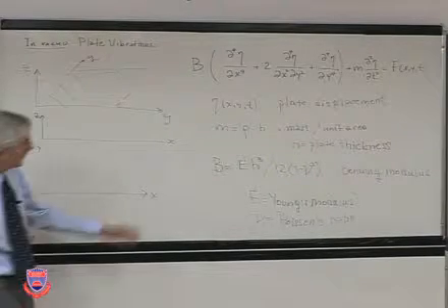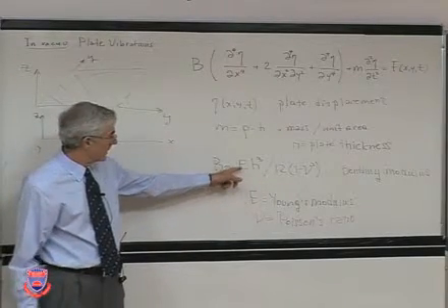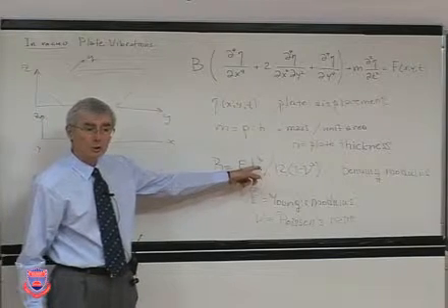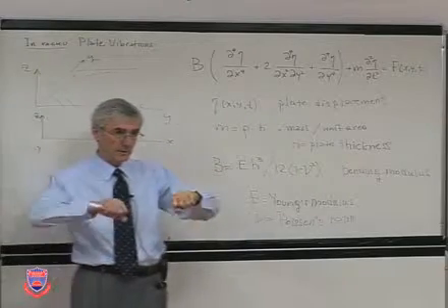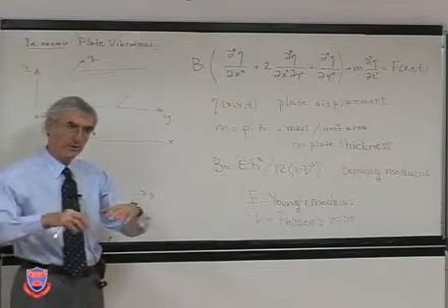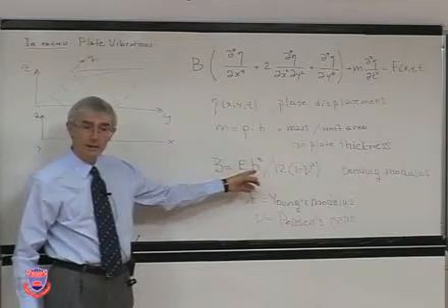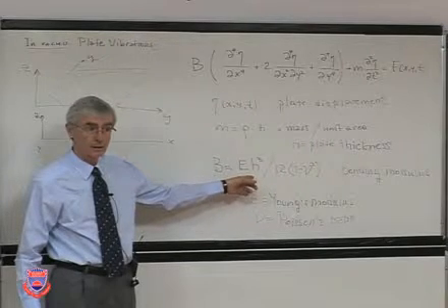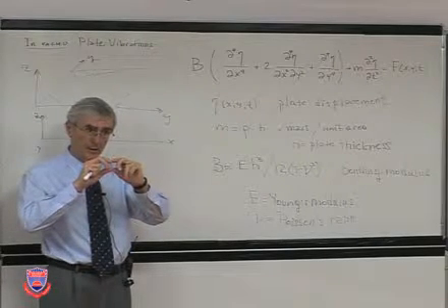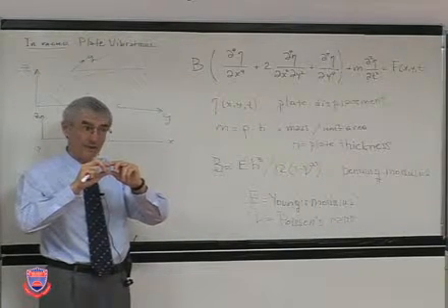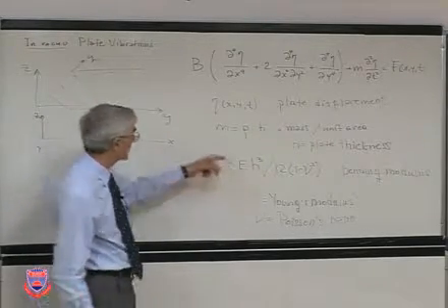Now, think about this for a second. See what these all tell us. Young's modulus, cubic of the thickness. Remember Young's modulus, it's the elasticity. It determines, it's a stiffness basically. So the stiffness goes up with the thickness of the plate. If you double the thickness of the plate, the bending modulus increases 8 times. So these are very important relationships in that sense.